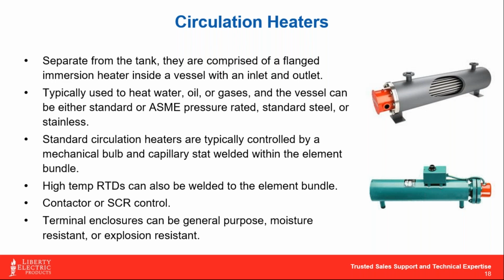And to control these, we can use pretty much any means. I mean, the most common are your contactor relay panels and SCR controls. I really like the SCR controls with these because when we regulate the voltage or current going to the heater, we can very precisely dial in that heat to literally within tenths of a degree. So your control with an SCR is excellent. And it also soft starts the heater to help add more longevity to it.